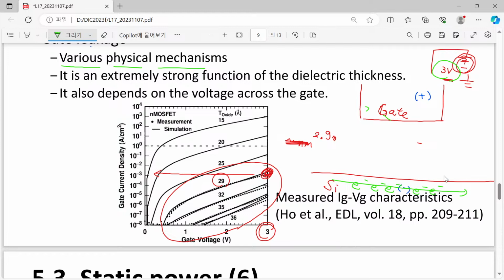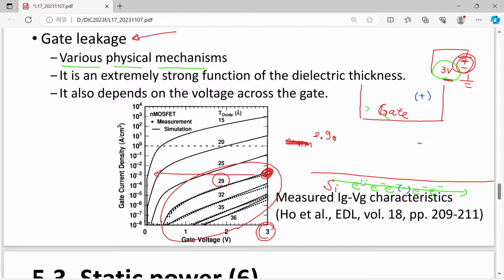It's not like in the silicon channel. It is just quantum mechanical tunneling into certain defects inside the oxide, and once again coming to the gate part. Because we have applied quite a high voltage, relatively high voltage, to our gate.